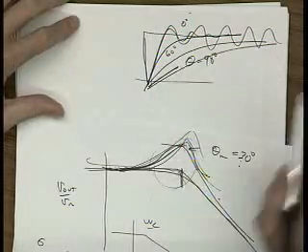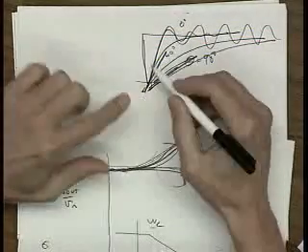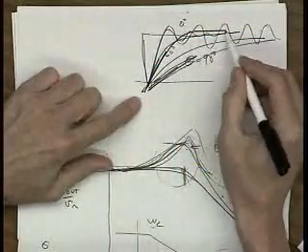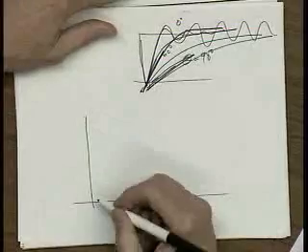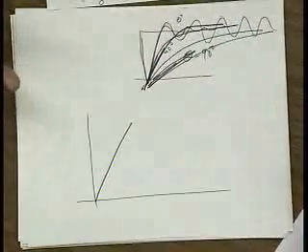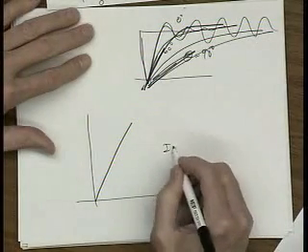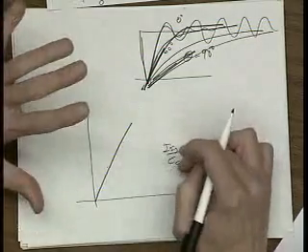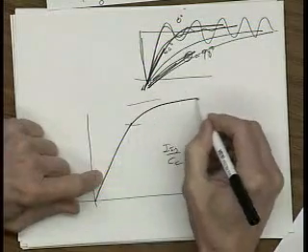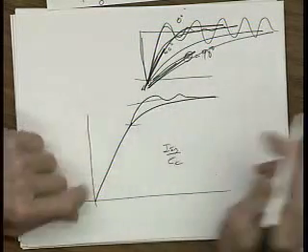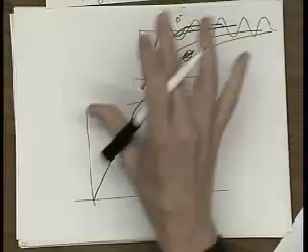Well, this is almost independent of slew rate. I shouldn't draw that. Slew rate will be the same. It's after we get out of slewing that I'm talking about here. This is the response. So that's a good point. The slewing stuff will be the same if we don't fool around with C sub C and ISS, right? This just comes from ISS over C sub C. That's how much current is driving the capacitance, the large capacitance. It's after that period, this last part here, that's going to get really slow. So slew is kind of one thing, small signal settling is another thing. This is all small signal settling I'm talking about here.